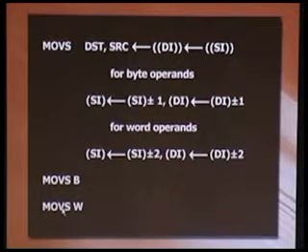This addressing scheme implies that the offset of the source or destination operands must be put in the registers SI and DI before the instruction is executed. In addition to performing the indicated operation of moving the contents of source operand to destination, the instruction causes the contents of SI and DI to be decremented or incremented by 1 or 2 based on the contents of the directional flag DF and based on whether it is a byte or word oriented instruction.